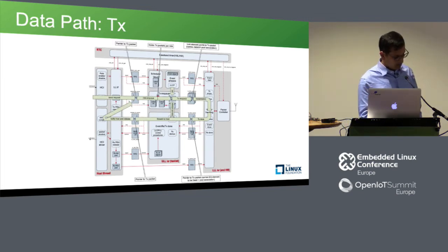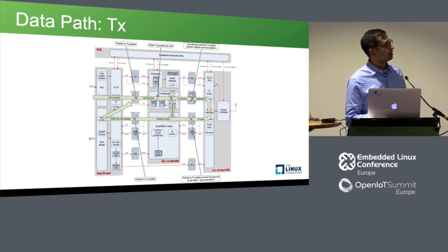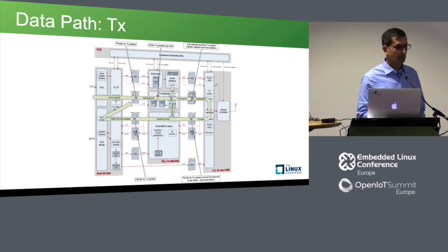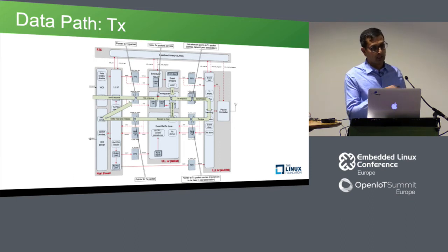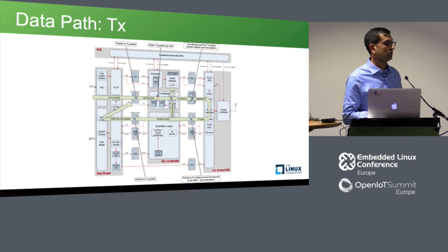On the TX path, again, there would be an HCI command, which then goes into a fixed size, fixed length FIFO. That's because in the HCI you have a read buffer size. If you say, for example, 10 TX buffers, then the 10 is going to be shared across your connections. So all that is needed is just a fixed length FIFO for the TX. But then once it's received by the upper link layer, it's demultiplexed into connections. So if you have 10 connections and you had 10 TX packets, each one for those connections, then they are demultiplexed into those connection contexts.